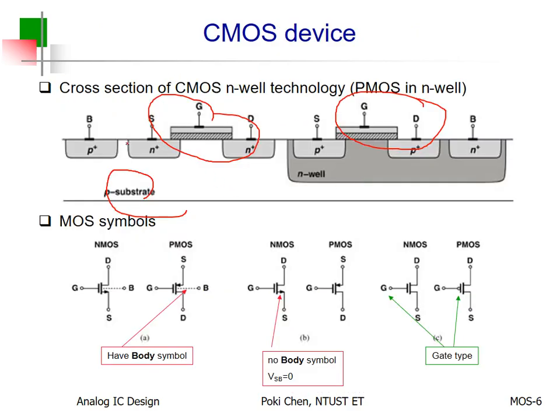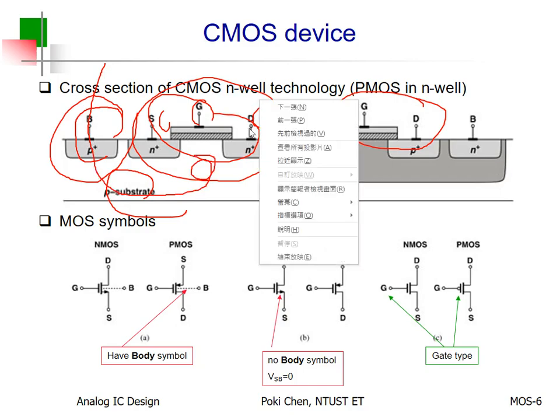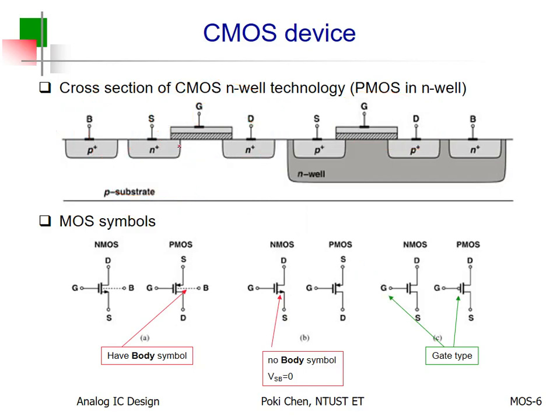Okay, let's go further here. This is the key idea. You cannot apply your voltage directly to the channel, to the body. So beside your main part, you have gate, your source, you have drain. Beside them, we have a body contact. Indirectly, you can apply the voltage here, then conduct to there. That's it. Please also keep this in mind. There is no way to directly apply voltage.